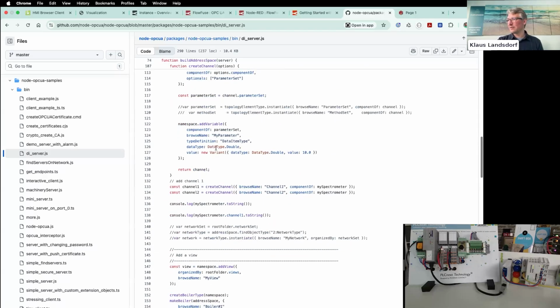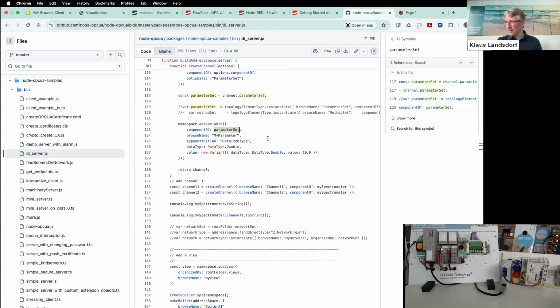And like here, if you see the parameter set, which is an optional thing of the device specification, that means you get a flat list in your device, in the best case, of all or about all parameters of the device. So if you have a more human readable structure in your OPC UA server, which is logically and hierarchically organized, then you can also provide from that specification a flat list of all important parameters to everybody who wants to communicate with your device.